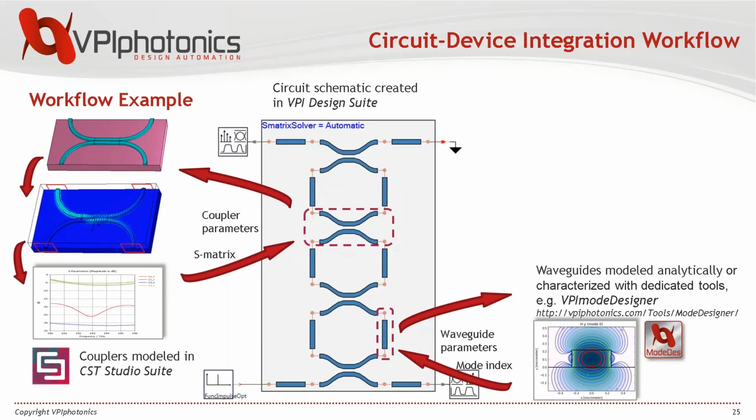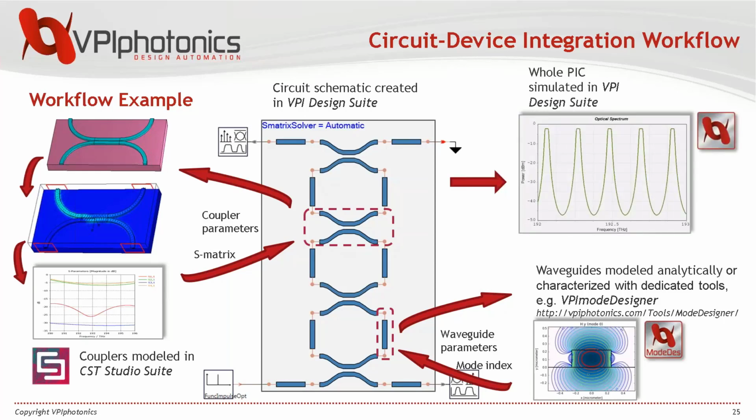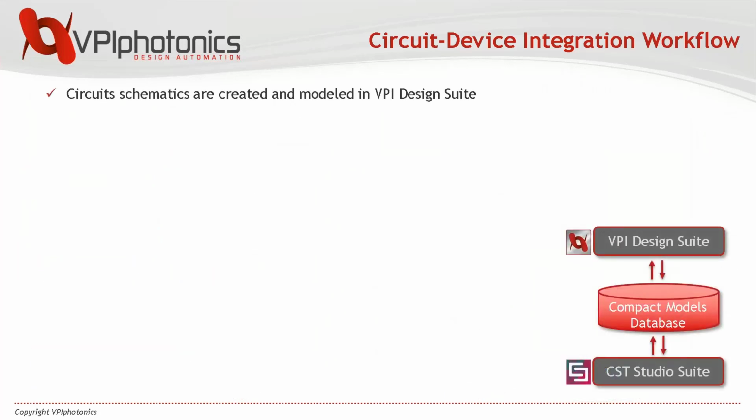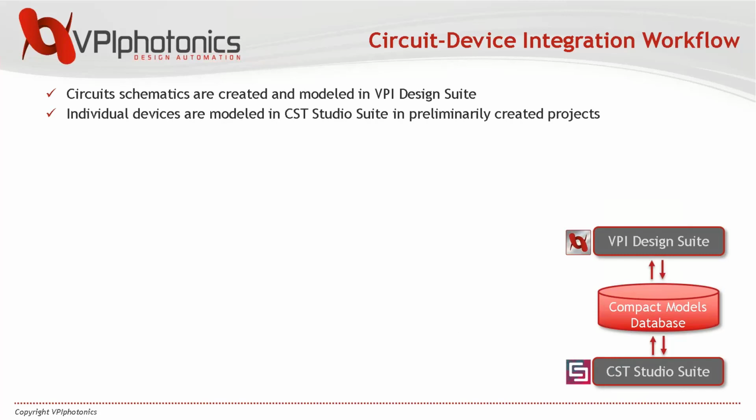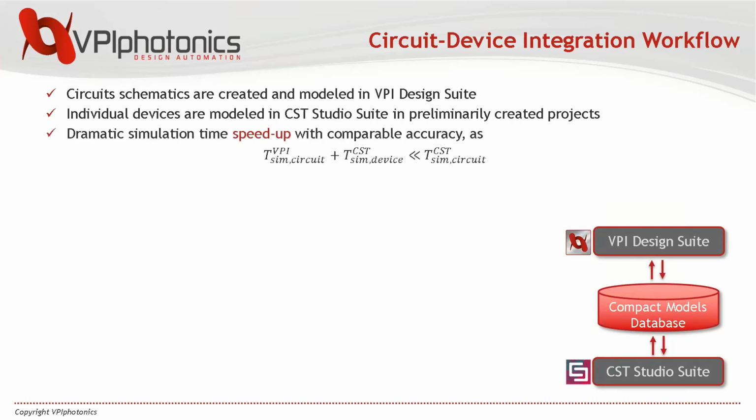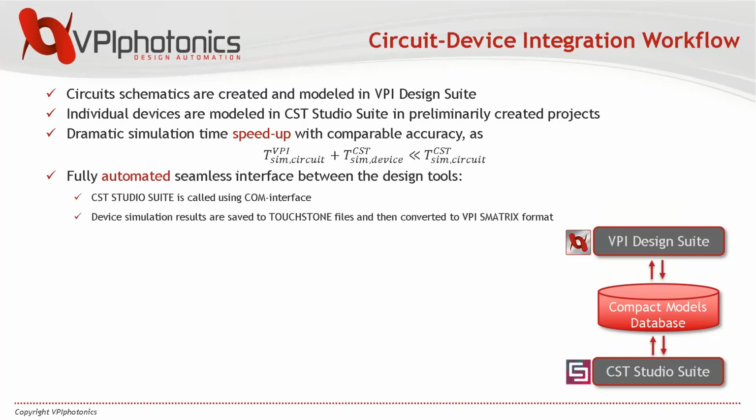Afterwards, once we have all models in place, we can test the device and obtain spectrum and get characteristics of the design from the circuit simulator. So this separation of circuit level simulation of the PIC itself from device level modeling of its building blocks allows for accurate modeling of large scale PICs on a single personal computer and provides sufficient accuracy. And it is worth mentioning that this process is fully automated, so there is no need for manual transferring and converting files between different simulation tools. So it is done all automatically.